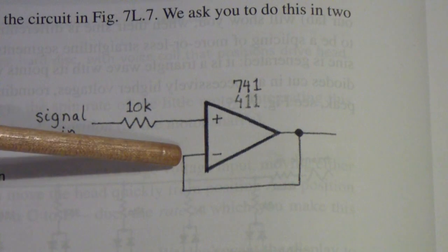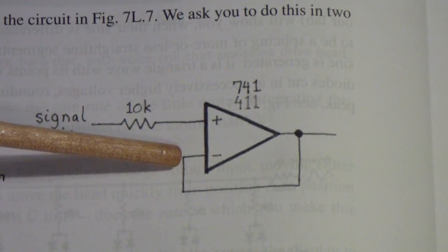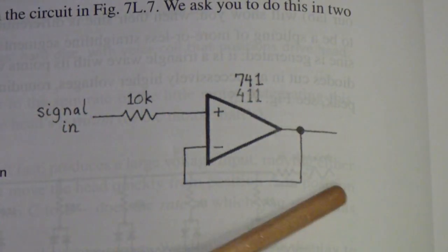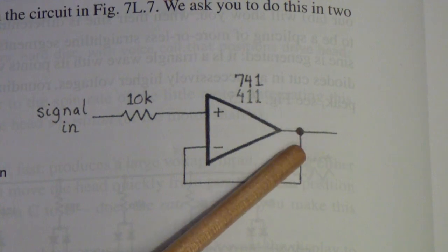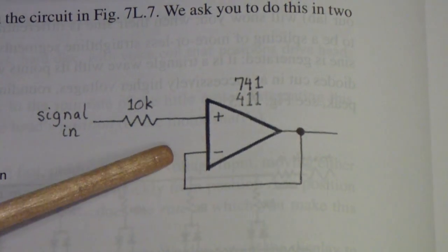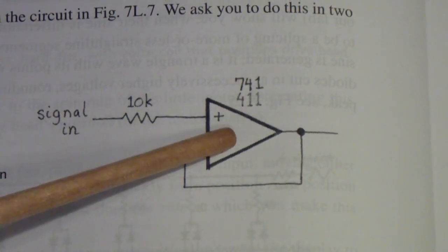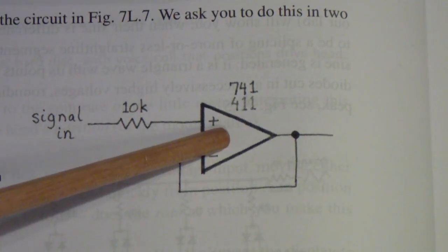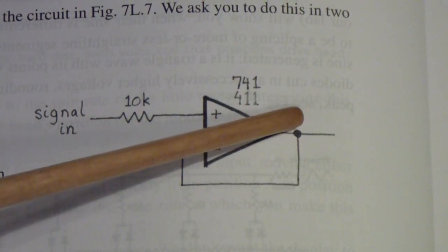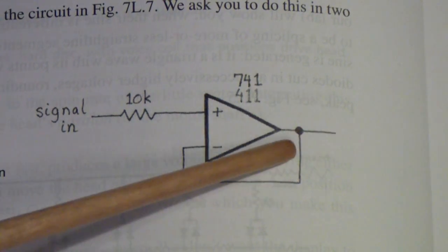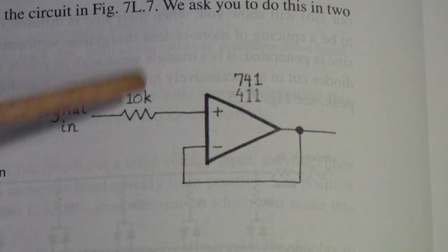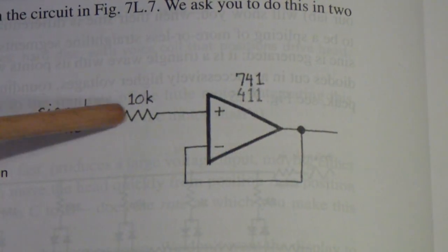voltage division. And one reason that I mentioned earlier how this happens is, understand that, once again, this node voltage multiplied by the open loop gain of this amplifier is equal to the output voltage. Now, the output voltage will also be influenced by the input.